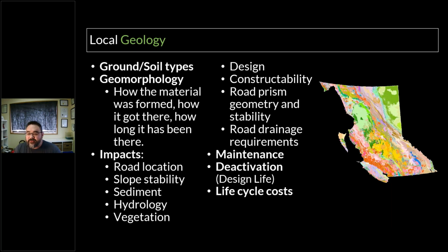So the two broad considerations are how the geology influences the overall road location, and how it impacts the detailed road geometry. Both of these, as always, are impacted mostly by water. At the landscape level, this is water management: interception, redirection, concentration. You get sensitive areas, streams, or saturation or drought. But at the local level, it's cut and fill angles, road benching, and end haul of materials, like moving excess cut material along the road, and then how you're going to spoil it.